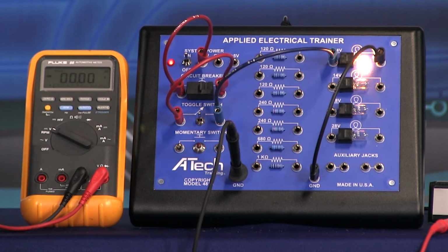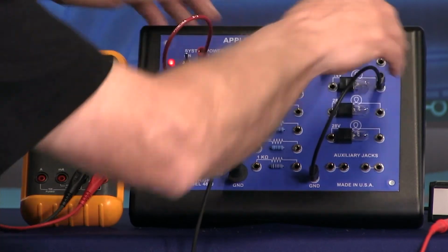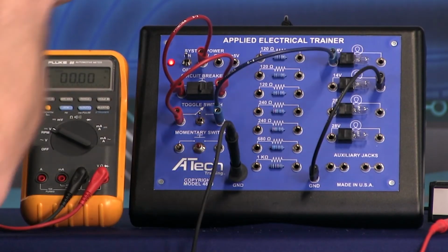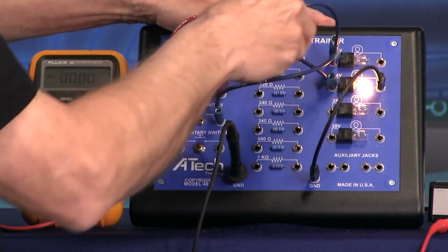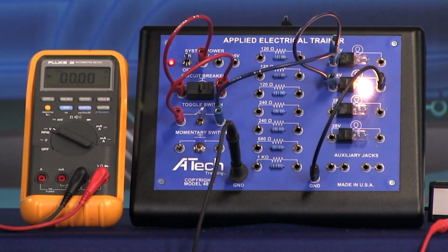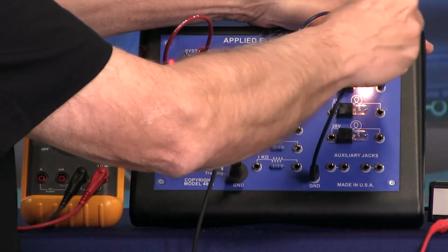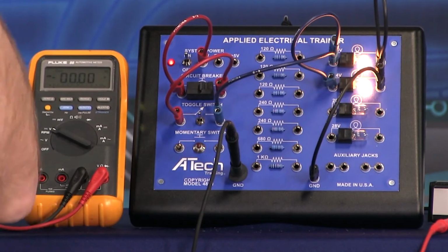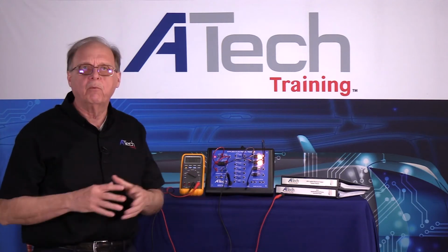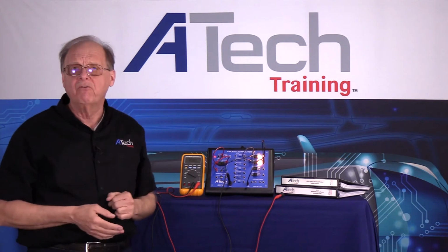Now, the next thing we can do, having a little fun with this, I'm going to put my black lead here. I'm going to take this one. And notice I have one bulb lit right now because I haven't provided a ground to this one. So I'm going to do a parallel circuit. Now watch. There's a parallel circuit. So in other words, we have two circuits up here. We're going two different paths. The voltage across each path should be the same, all right?